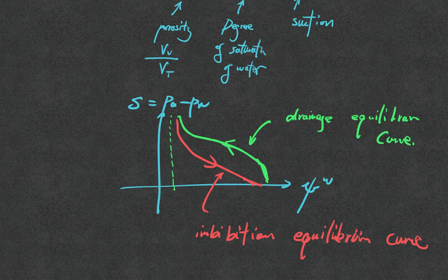This whole curve doesn't start at zero degree of saturation. There's a residual there. What it means is that you can increase the suction, but at some point there's a droplet of water that is isolated and you cannot make it completely dry. The only way to get out the last portions of the water is through maybe phase change.